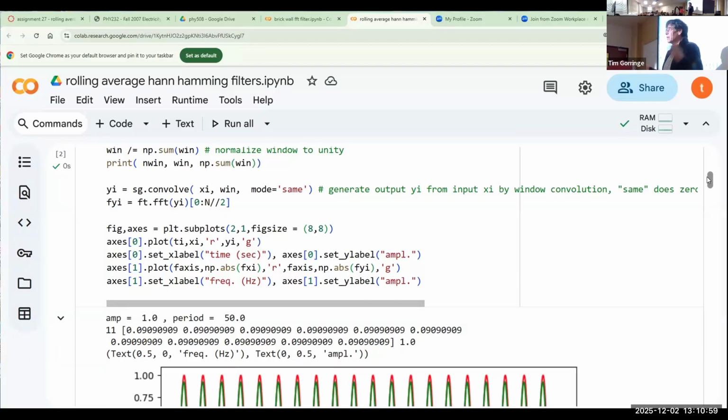Supposing I'm in the middle of the array, at sample 500. I'm going to convolve using sample 500, the 5 samples to the low side of that, so 499, 498, 497, 496, then 5 samples to the high side of that. All those samples exist, so I can just calculate the convolution.